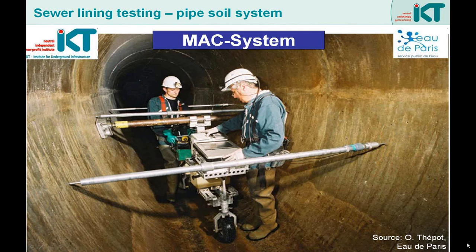The measurement can help to identify a suitable rehabilitation technique, for example injection to improve the soil and lining to improve the pipe. But the measurement can also help to verify the success of any rehabilitation. We can compare the results before and after rehabilitation, so success can truly be quantified.